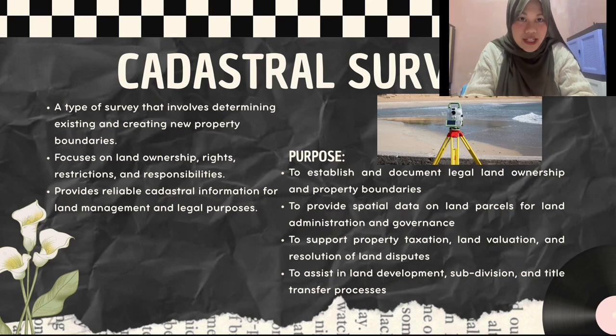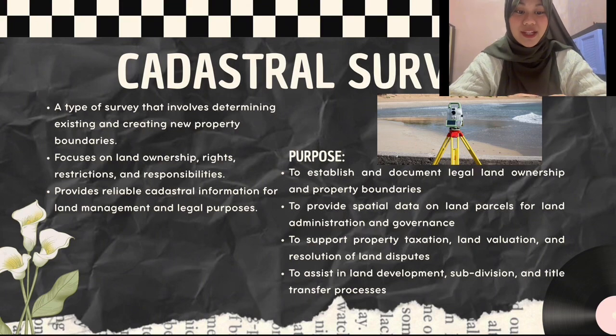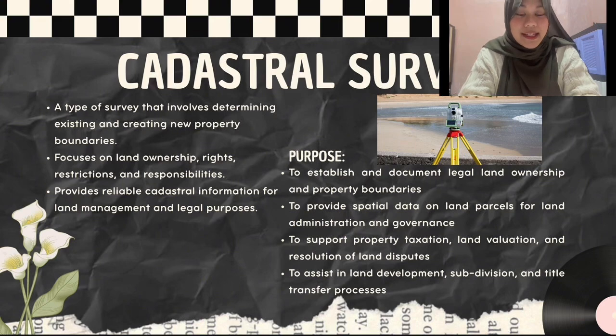And the purpose of cadastral survey is to establish and document legal ownership and property boundaries. Next one is to provide spatial data on land parcels for land administration and governance. Third one is to support property taxation, land valuation, and resolution of land disputes. And the last one is to assist in land development, subdivision, and title transfer.